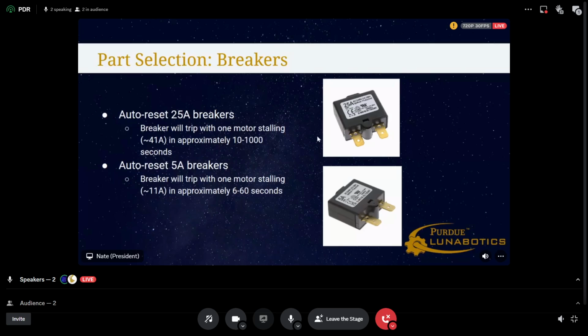Well, theoretically, it's not in this slide deck, but there's somebody working on their senior design project that is basically a battery protection circuit. Theoretically, it'll do individual battery cell monitoring, and it will be a secondary trigger to the main relay when you get below a certain voltage. I believe for a 6S battery, it's about 18 volts. So that's how we plan to do it now. Do you have concerns with that?